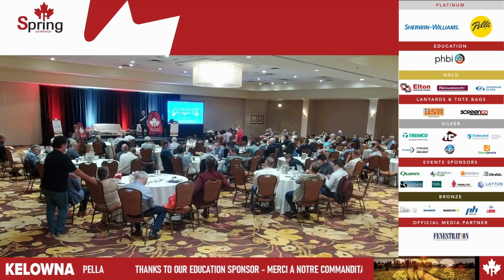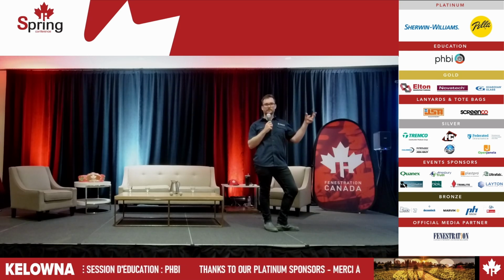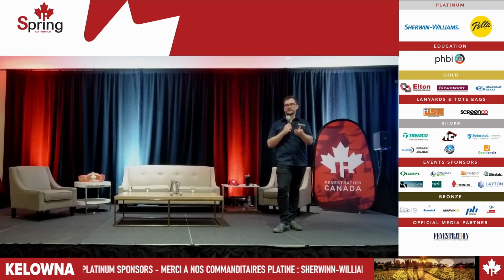So after those windows are installed, putting the tints on after, is that what you're getting at? No, during the manufacturing process. And yes, we could do it after as well, but during the manufacturing process. Yeah, we all base it off an NFRC or third-party test data, which looks at the standard sizing for the U-value and solar heat gain coefficient. That's what we're putting into our model here as well. So yes, adding that additional tint does reduce the solar heat gain.